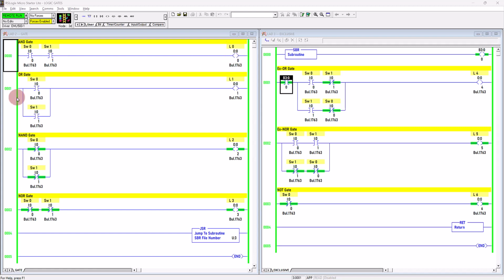As for the OR gate, all the virtual switches remain untriggered because the external physical switches are not pushed to close, so the normally open remains open, which is 0. Normally open for this one also remains 0, which is open. So 0, 0, the output will be 0, meaning de-energized. The virtual output coil is de-energized.